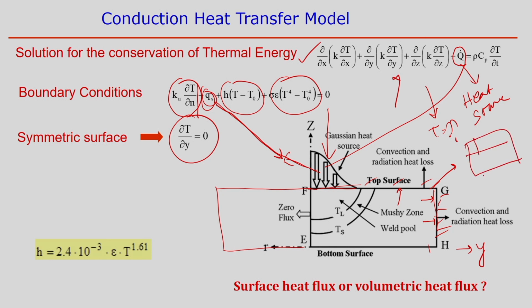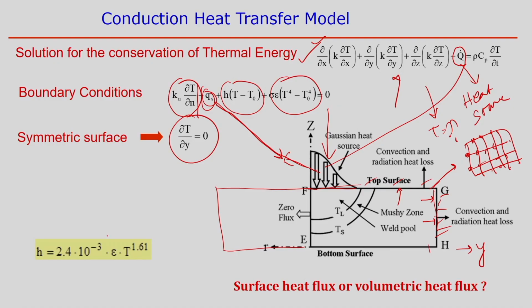in the finite element model, these are the elements and nodes, the discretized domain. So, you will get the temperature value at each node point. Then finally you can make it a distribution of the temperature over the domain. So, this is the output, but here you can see this is the governing equation applied over the domain. If it is a symmetric surface, you can define the symmetric surface, then you can reduce the computational time, the number of elements and number of nodes in numerical methods. But if a symmetric surface does not exist in a particular problem, then you have to consider the whole domain.